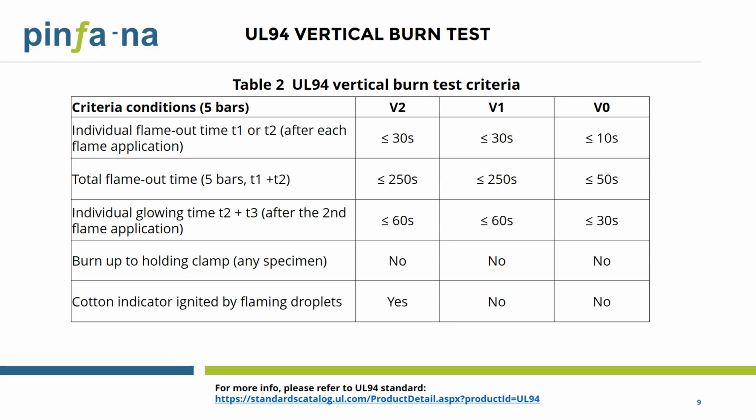UL94 test with a specific performance target is a pass and fail test. We'll discuss evaluating the probability of a pass and fail test, and why the sample condition prior to the test is important, on a later slide. Let's take a look at a quick demonstration video of the UL94 vertical burn test next.